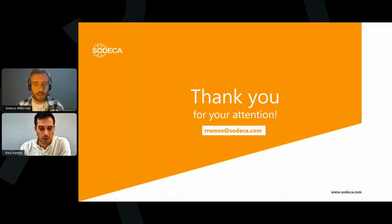The first question is: what is the recommended air changes per hour while designing the ATEX system? I think you already explained the formula, no? Well, yes, we explained the formula, but the standard does not determine a specific rate. So at least you can calculate the formula as a minimum airflow, and then you establish that for this case we need 10 times or 8 times the airflow we calculated, to have a higher dilution. That's it.